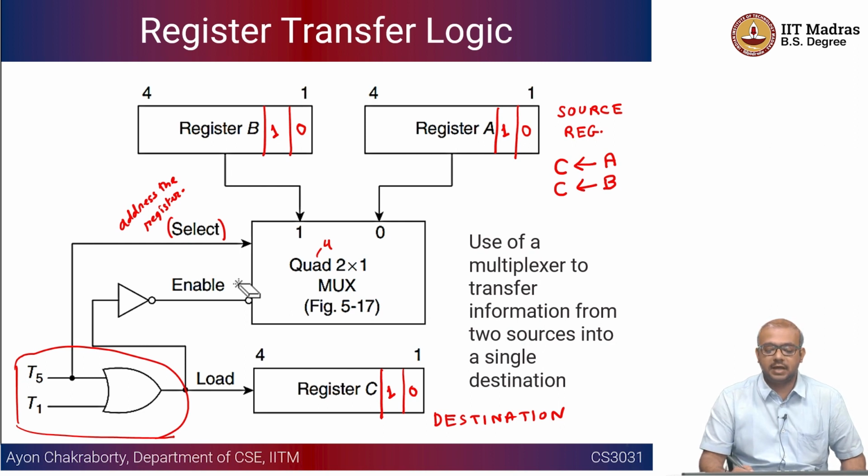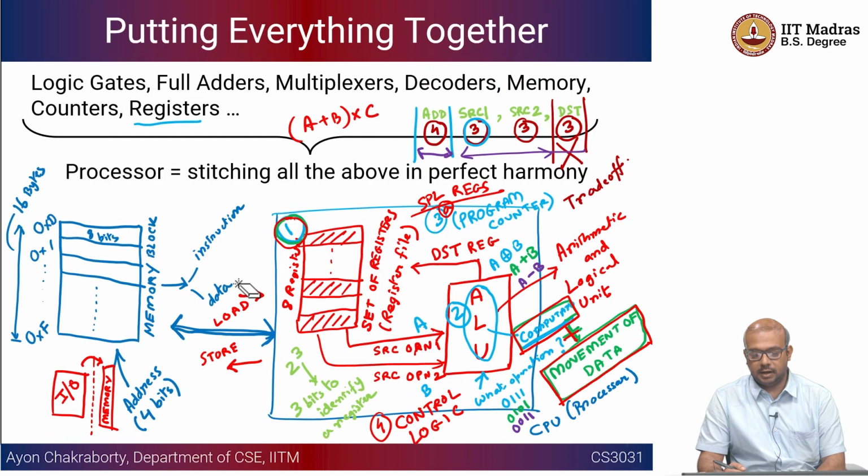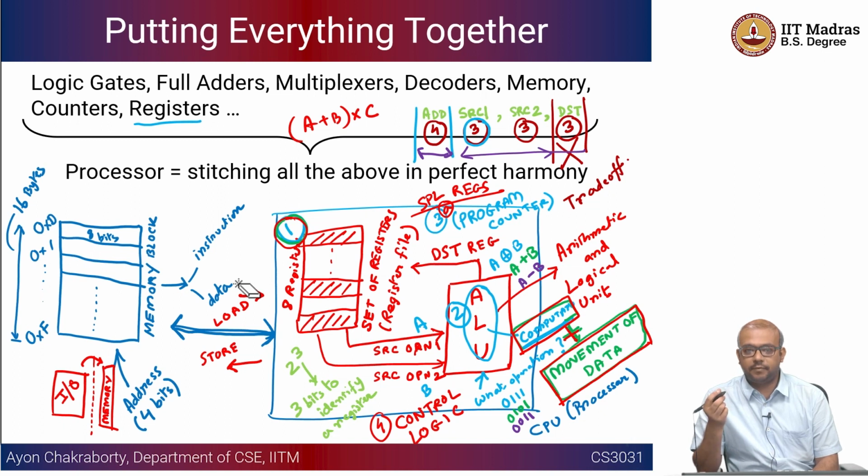This register transfer, as I told you earlier, is not going to happen all the time, right? As I told you in this particular figure, there are some instances of time which are very specific. Only at those points in time are you going to do the register transfer, as mandated by the control logic. The control logic is going to mandate that at this point of time the contents of register X have to go to register Y. After that they should not talk to each other or even interfere with other register transfers. Okay, there's an isolated piece of time and at that time period this transfer has to happen. It cannot happen earlier, it cannot happen later, because whatever instructions we are going to be executing inside a computer have very strict timing limitations and ordering.